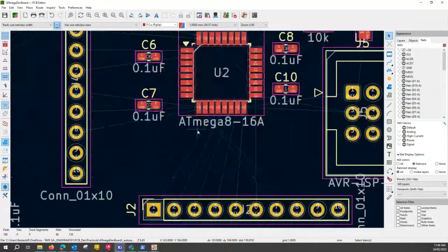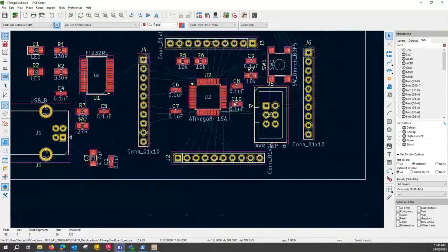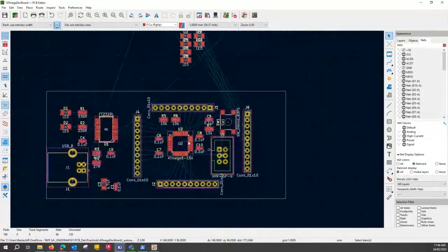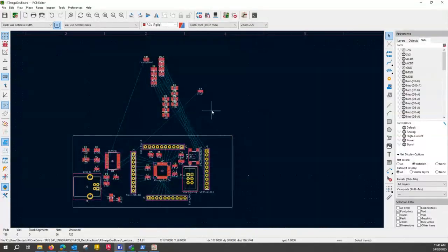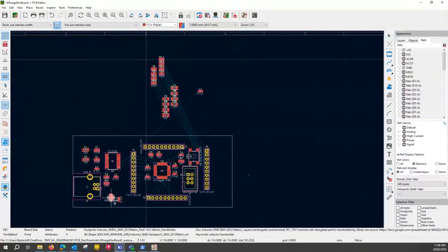Now, obviously, at the moment, you've got those nets going through components, and it's a bit of a mess there, but you just need to organize your components somehow. You've got to arrange them first, and then you start moving them exactly into positions you want them to be. So, ferrite bead, obviously near power supply somewhere.